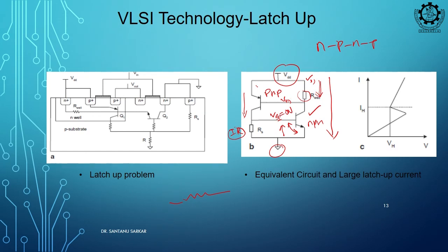So, there is some drop and now VBE on will start growing. What is happening? First, one current flows. So, when one gets on, this in turn will turn this on. So, this will become a positive feedback, getting my point?